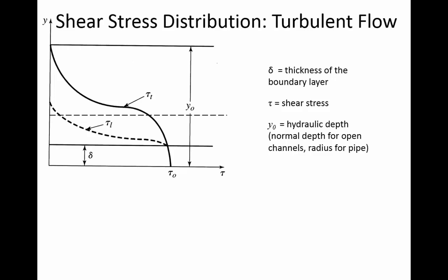So at a certain distance from the edge of the pipe, if you've got fast-moving water, then there's a lot of shear stress there. If you've got slow-moving water, then there's less shear stress. And so the magnitude of the shear stress, it's sort of reaching out into the flow. The faster the water is moving, the influence of the pipe edges' resistance is felt deeper into the flow when the